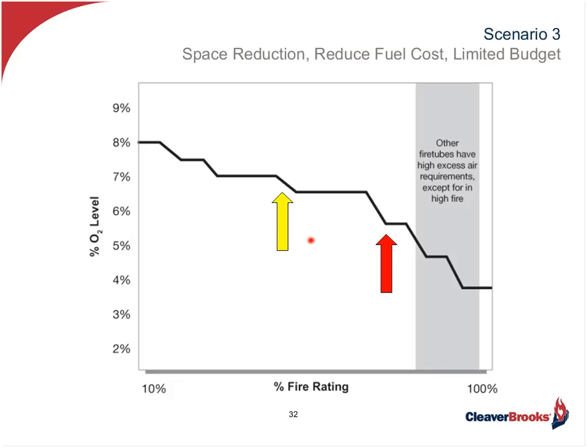But the main cause is the fact that these boilers are spending time in this particular area of modulation, below 50%, cycling on and off, when they should be over here at the low excess air level and much higher efficiency. This is how they were sized, but this is what the load dictates.